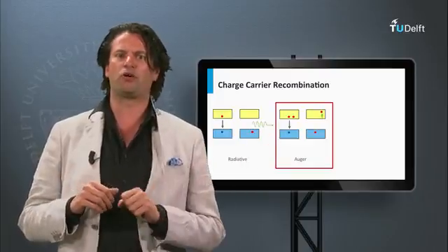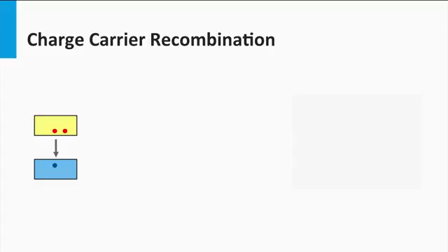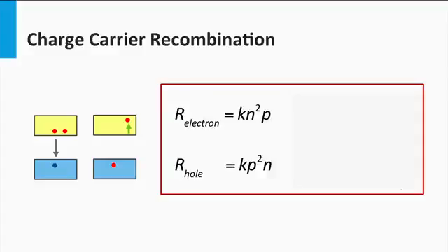Let's consider Auger recombination. Auger recombination is the process in which the momentum and energy of two recombining hole and electron is conserved by transferring energy and momentum to another hole or electron. This electron is excited in higher levels in the electronic band. This excited electron relaxes again such that the energy is lost as phonon modes. Phonon modes are lattice vibrations and are nothing different than heat.